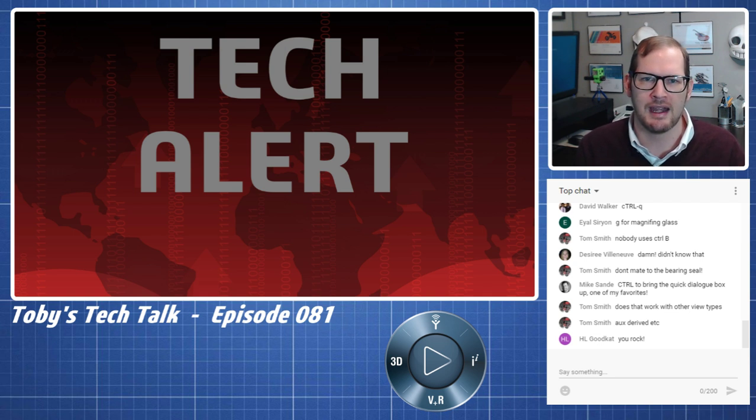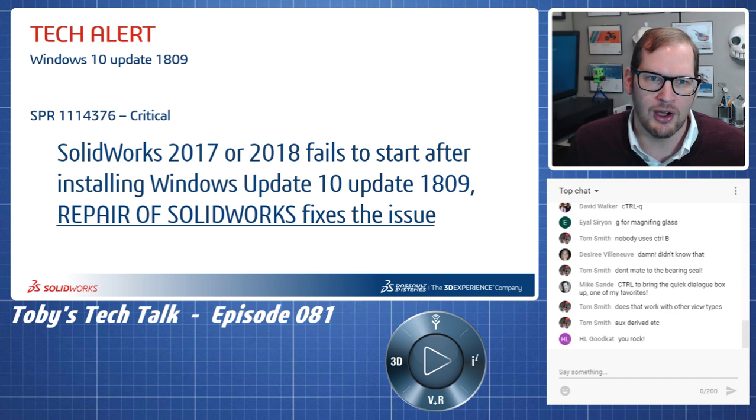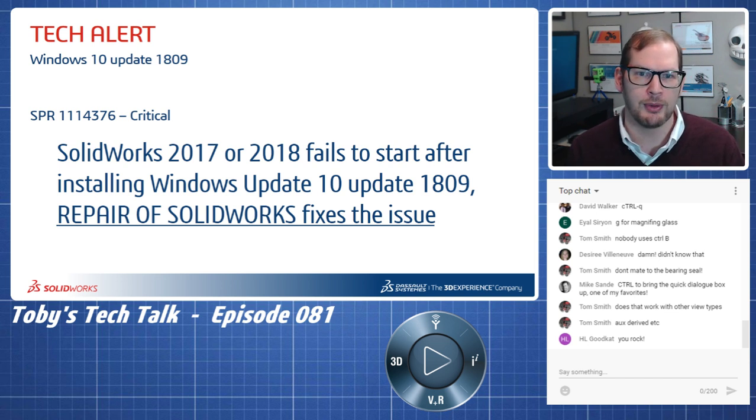We're kind of coming to the end of Q1. This is typically when things are a little bit slower in the world of tech support. But I always have my ear to the ground. I'm always looking for maybe any cases that are affecting a lot of our users. The only one that really comes to mind was that Windows did push out an update for Windows 10. The update is known as 1809, and you can see here in the description that it was causing SolidWorks 2017 or SolidWorks 2018 to fail to start.